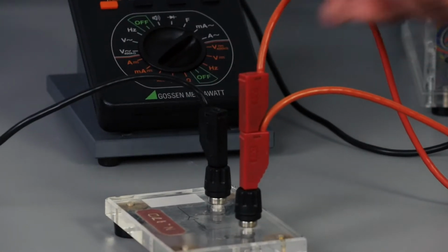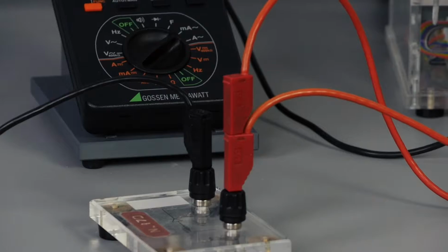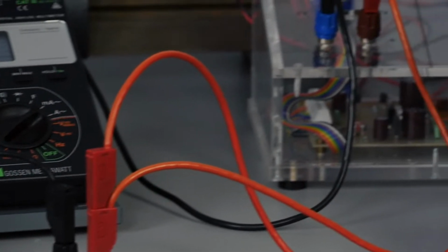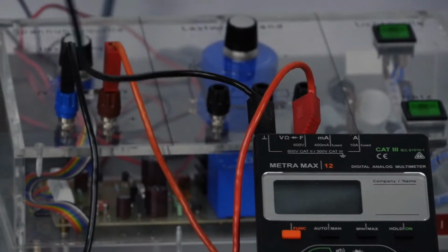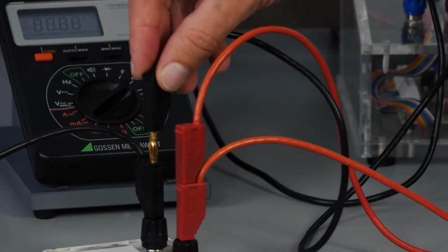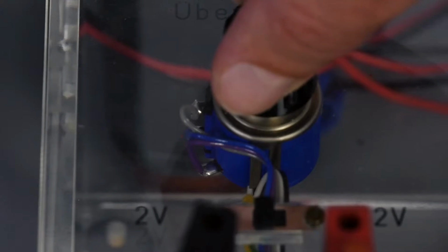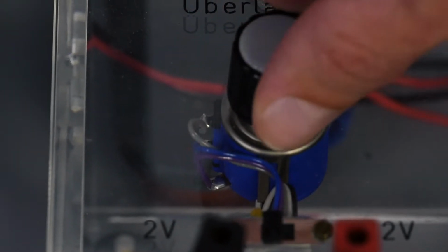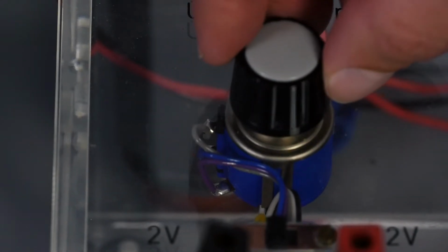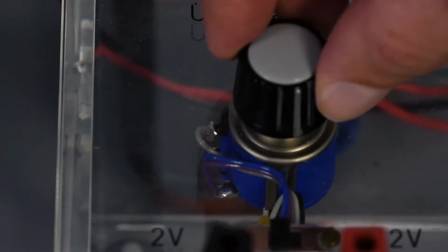First, the IV characteristic of an unlit semiconductor diode is taken. Set up a circuit in which the diode mounted on the acrylic holder is connected to a voltage. Both the voltage and the current through the diode should be measured. The ammeter is connected in series, the voltmeter in parallel with the diode in the circuit.